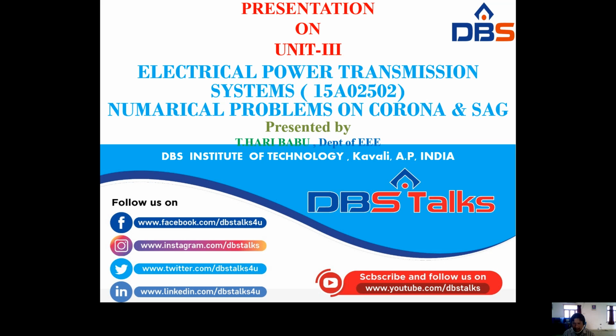Sometimes they give the K value, then you have to determine V1, V2, V3, and then the string efficiency. Sometimes they will give V1, V2. From that V1, V2, you have to determine K and then V3, then the string efficiency. Sometimes they give the K value and the V3 value. For that, by using K and V3, we have to determine V1 and V2 and then the string efficiency. So these are the individual problems.